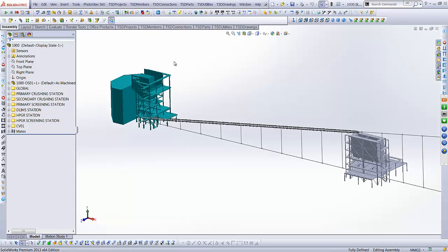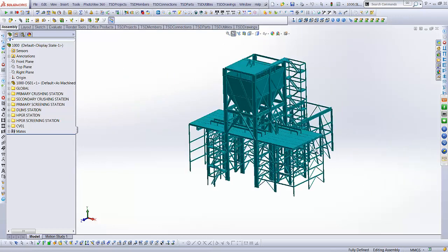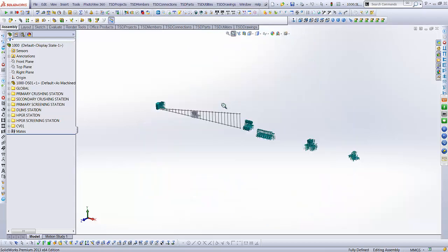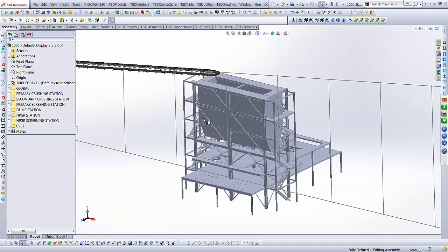These models themselves are quite large, and I've got several of them in this project. You can sort of see what's in them. Now they were modeled using Tekla Structures, and we've just brought them in to model around them. Okay, so yes, you can bring in models from Tekla Structures. They have no smarts, but they are there for us to work with. We also can bring in Tekla Structures models that have smarts through SDNF, or even through what's our analytical package, STAAD.Pro. So there is that way as well.